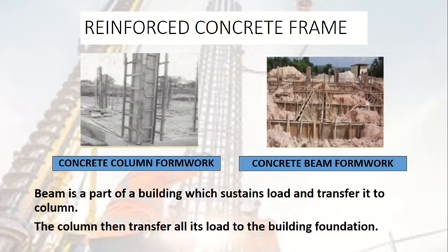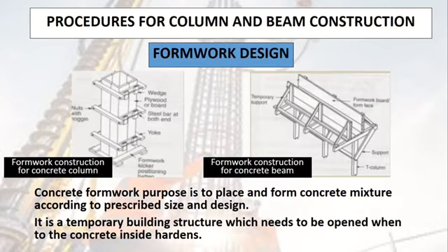Reinforced concrete frame. Concrete column formwork and concrete beam formwork. Beam is a part of a building which sustains load and transfers it to column. The column then transfers all its load to the building foundation. Procedure for column and beam construction.